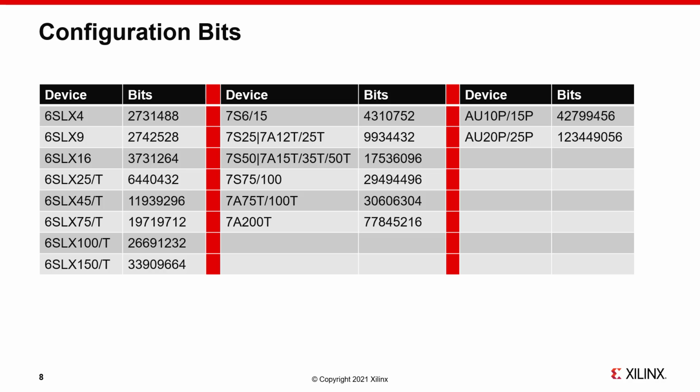Configuration mode and the number of configuration bits required are integral elements in transitioning the design to a different architecture. Knowing how you want to configure and what size storage is required to program is something that must be considered when selecting the final targeted device.